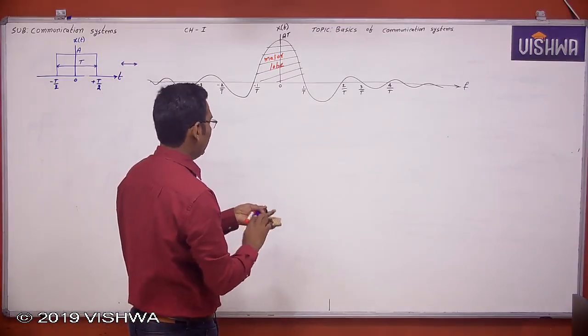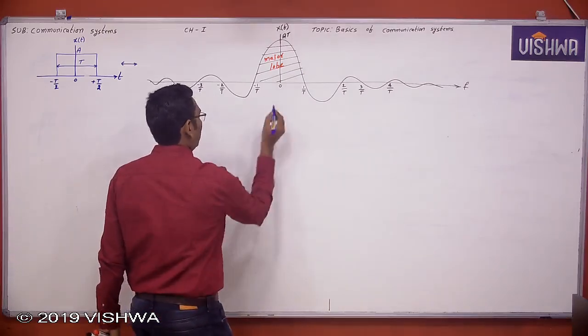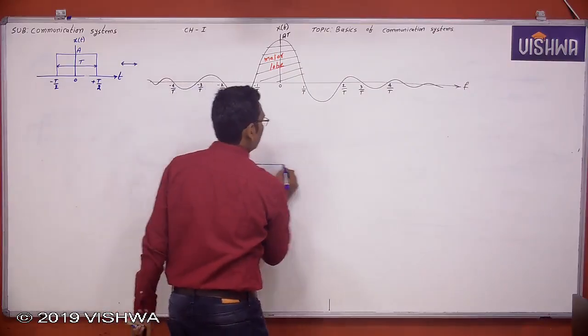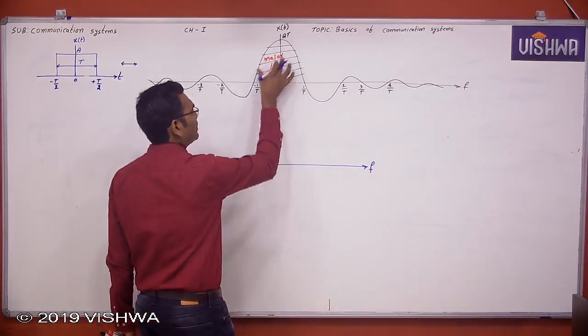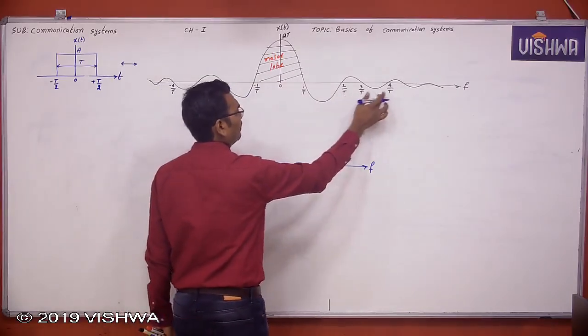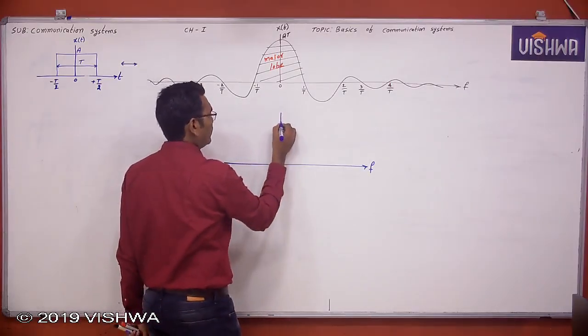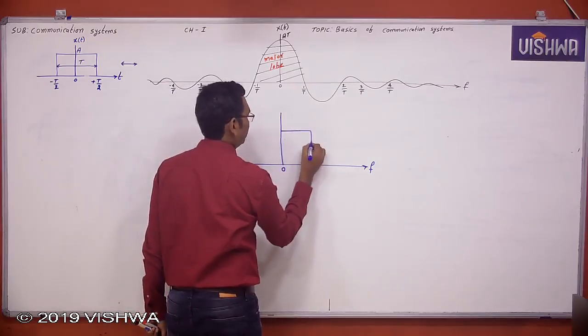So these insignificant frequency components are eliminated and only the significant low frequency components are saved. So now I use a filter. Now which filter? The low frequency information is to be saved. This is F, 2F, 3F, 4F, 5F and so on. So use the low pass filter.